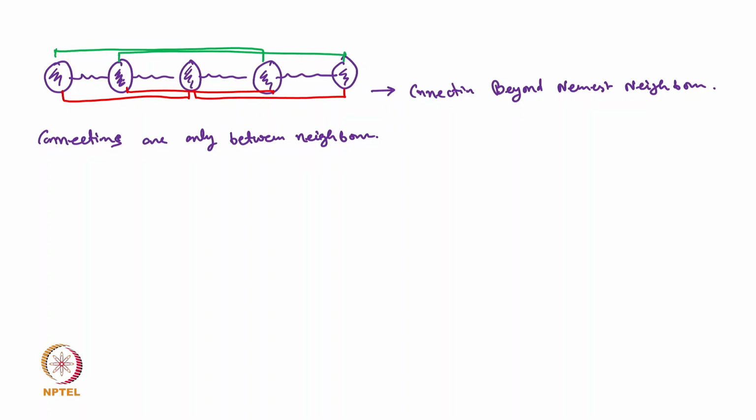Let's first see how we can write the equation of motion for the nth mass of that type of system. Let's say this is my nth mass. The nth mass can be written like this: m un double dot, that is my inertia term, plus the sum over j equal to 1 to n of kj into 2un minus un minus j minus un plus j.